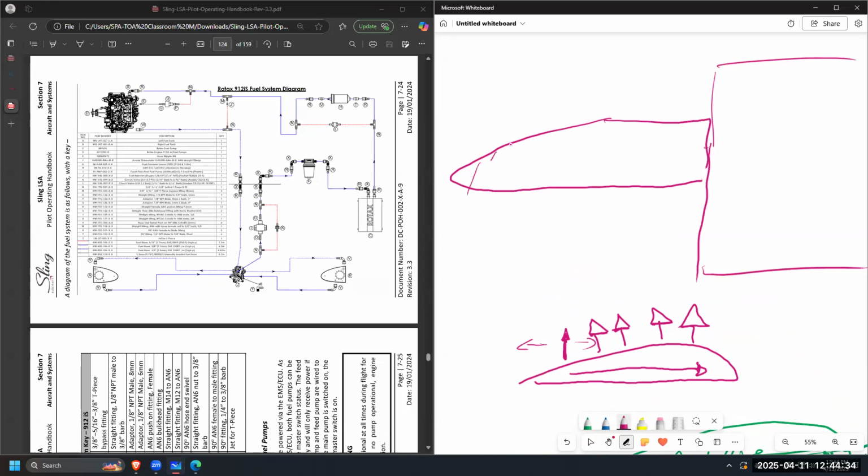This is how much surface you have to create lift, correct? If you're now increasing your angle of attack, what's going to happen? The center of pressure or center of lift, same thing, is going to move, for example, from here to where? Forward, to here, right? And it keeps moving forward at any given point, really.